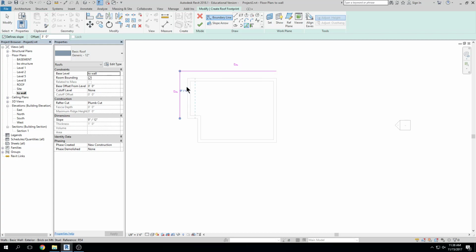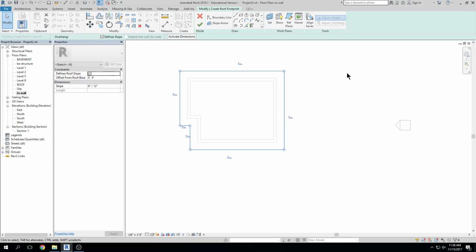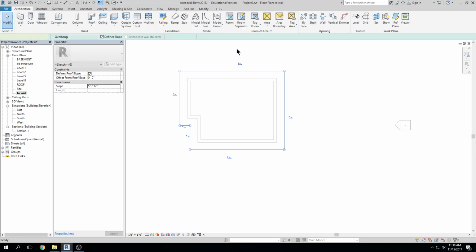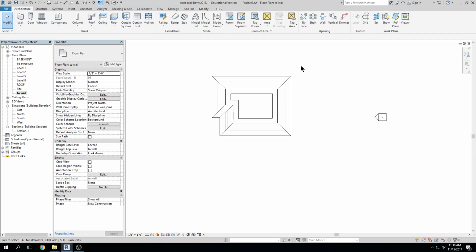Click. If you offset it to the inside, it won't work, right, Corey? You'll have a tiny little roof that sits on the inside. Trim, TR, right? I don't get everything perfect the first time I do it. Tab, click, and I can change the slope of all these from 9/12 to 5/12. Enter. I hit finish. There's my little roof, but my little roof is cut off, right?